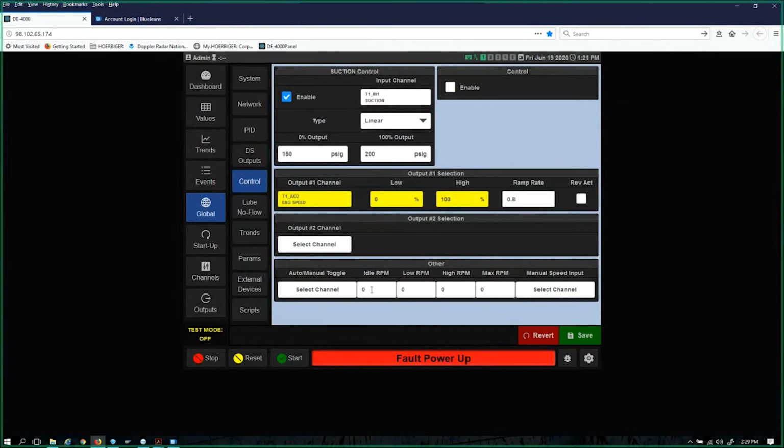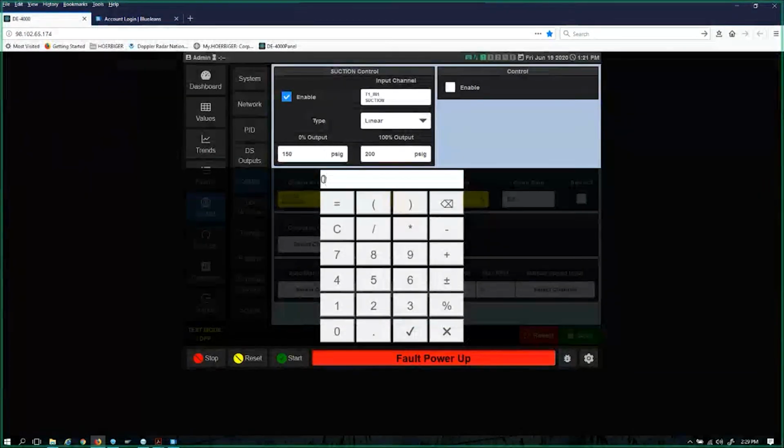What I'm going to do is assume that if I send the engine a 4 milliamp signal, it'll go as low as 800 RPM. Now, the 3500 by default generally only goes as low as 1000, but most people do go out and program them to where they'll idle at 800. So in this field I'm going to tell it 800.